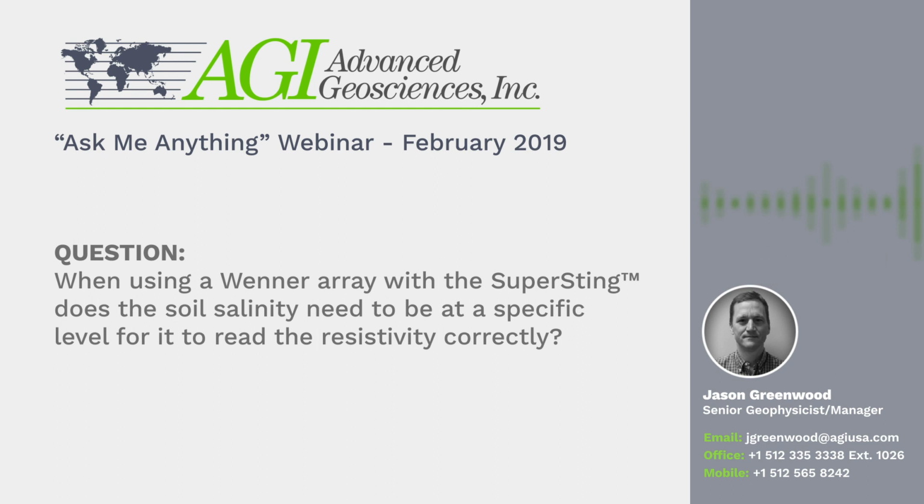So okay, there's a question here about Wenner array data. When using a Wenner array with the SuperSting, does the soil salinity need to be at a specific level for it to read the resistivity correctly? That's a pretty open-ended question. Wenner array is typically used for 1D soundings. Let me show you what I mean by that. It's the lowest resolution array for tomography for 2D and 3D.